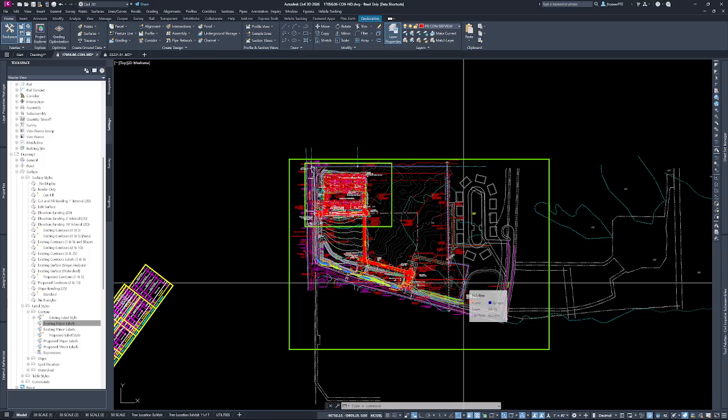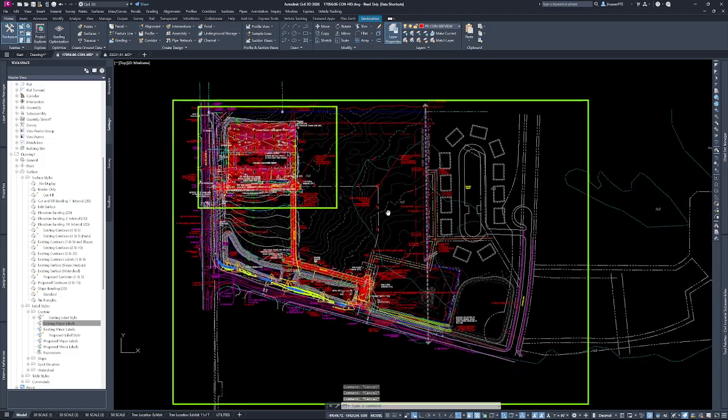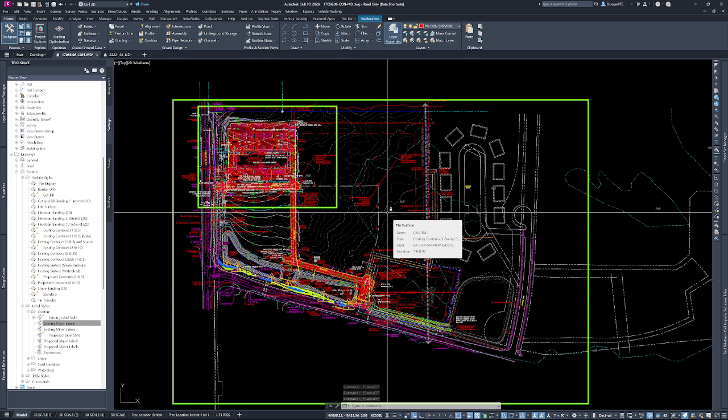One of the biggest things that slows down a drawing is a large surface. And really, the next two topics on my list kind of go hand in hand. First thing is to isolate and simplify your surfaces. I'm not a big proponent of doing this all the time, but there are cases where it's important to do it. You don't always need to see every single surface turned on, and I think most of us realize that already. Especially now, you can go in and we have a nice option to say no display. The surface is still there.